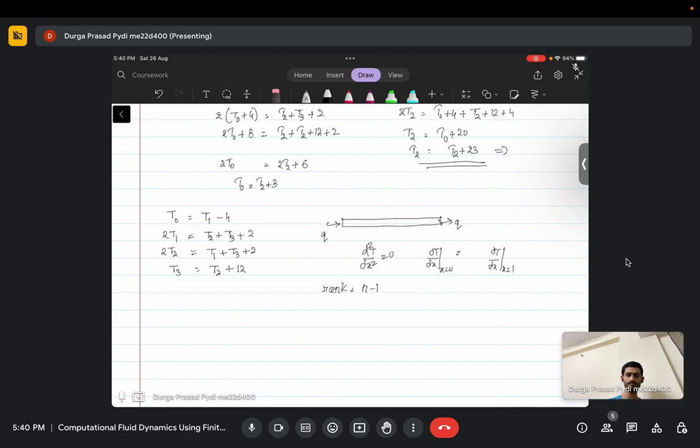So when you say to solve this equation we have to add another equation, that is our constant equation. Yes, you need to add some reference. It's simple. You just put T0 equal to some constant. This one new equation is sufficient, right? You just need some value to fix that constant. It can be anything. You can fix one of the boundary temperatures, or fix one of the cell nodes to have a certain temperature. That should be fine, right?